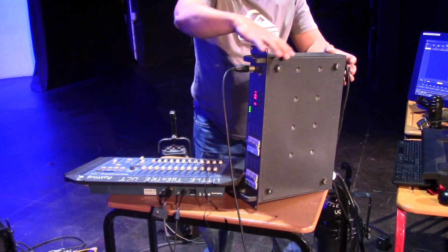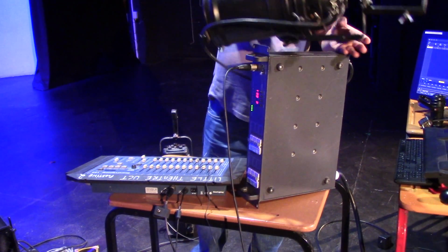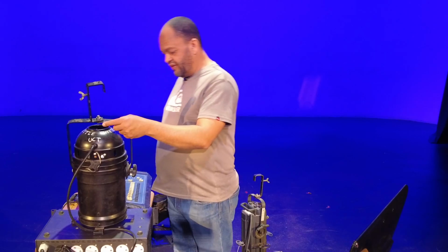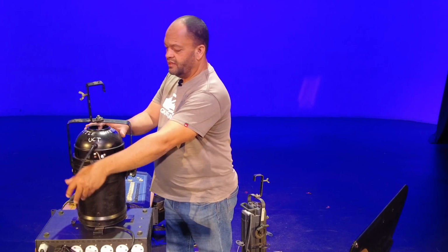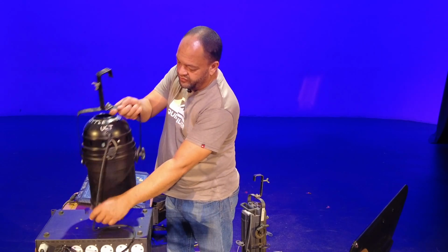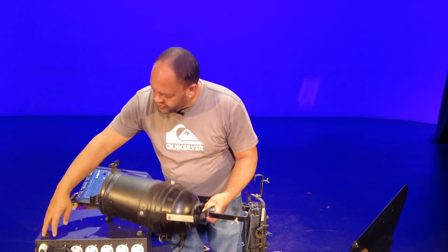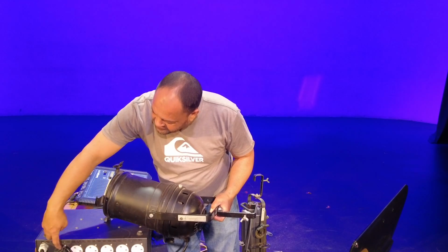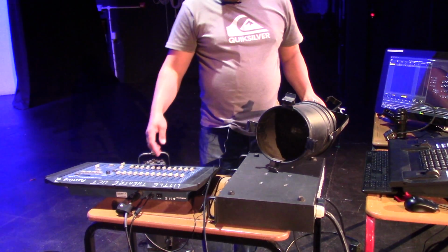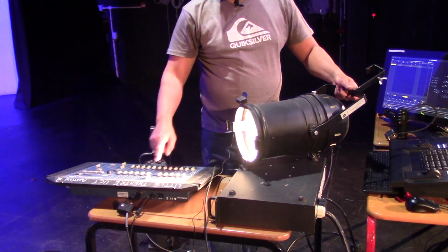Okay, then for us now to have control over this power, everything is connected: the lighting desk to the dimmer, and the actual light that you want to use is plugged into your dimmer. Because at the back of your dimmer rack the channels go 1, 2, 3, 4, 5, 6. On your lighting desk, as we plug into channel 6, we bring up channel 6. That will give you control over that light.